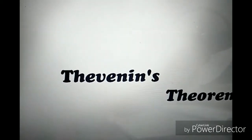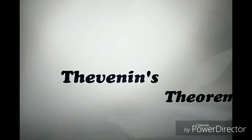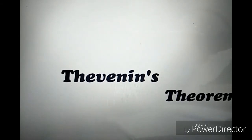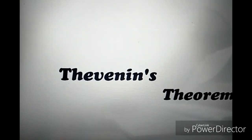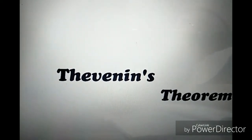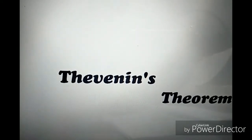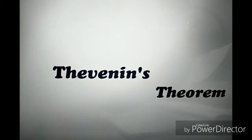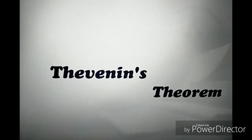The theorem is: any active linear bilateral network consisting of independent or dependent current and voltage sources can be replaced by an equivalent circuit consisting of an independent voltage source VTH connected with RTH in series, where VTH is the open circuit voltage and RTH is the equivalent resistance of the network as seen from the load resistance RL, with all internal sources replaced by their internal resistances.